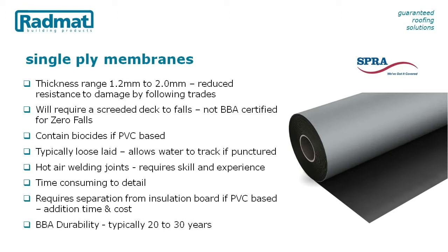No single-ply is currently certified for zero falls application, so will require a screed to falls to comply with building regulations. This adds costs and prolongs the program. For codes of best practice, refer to the Single Ply Roofing Association SPRA Design Guide.